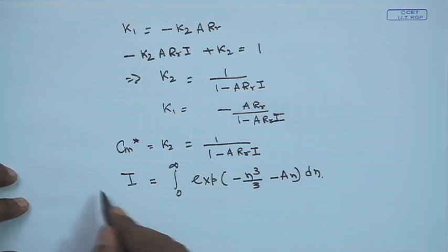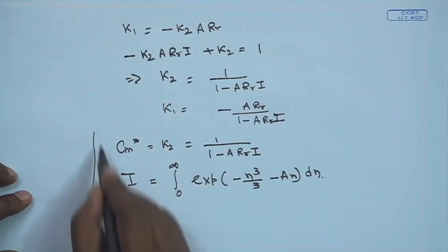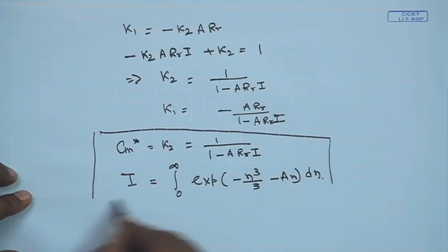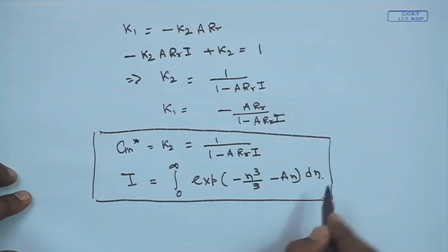So, these two relations are extremely important. Whatever we have done is that we evaluated the concentration profile in the mass transfer boundary layer as C star being a function of eta, which is a combined variable in terms of y and x, where eta varies as y divided by x to the power 1 by 3.